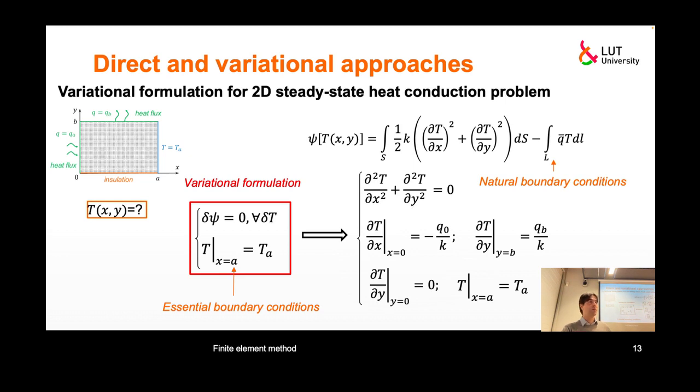And that's one of fundamental difference between those two approaches that is important for finite element analysis or for any numerical methods actually. We do not need to calculate second derivatives when we are using variational formulation. Practically, we don't need that, so we have a little bit more relaxed requirements to our function.